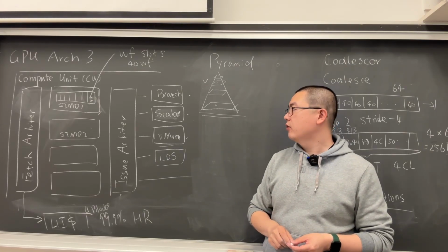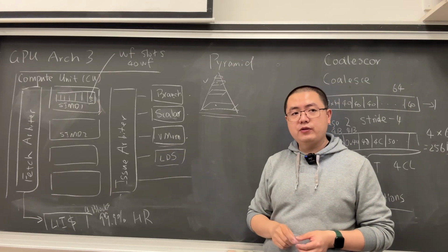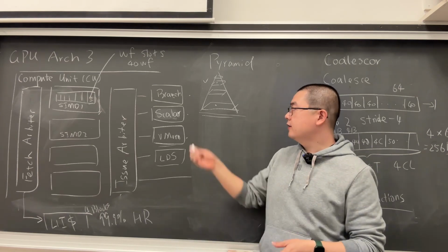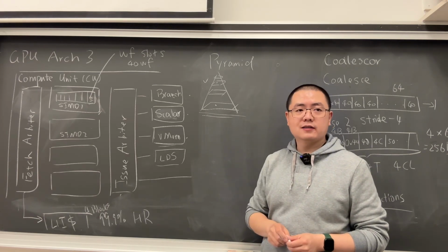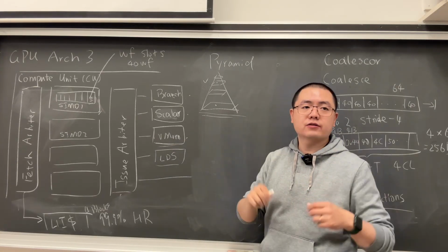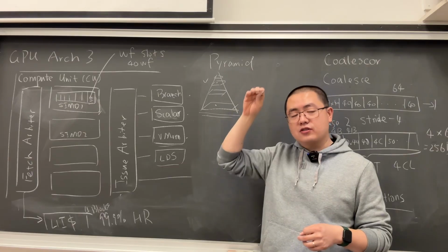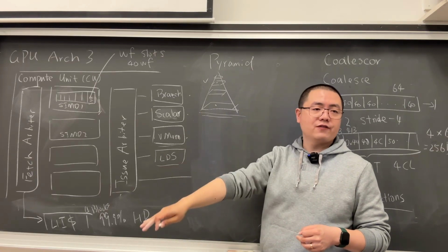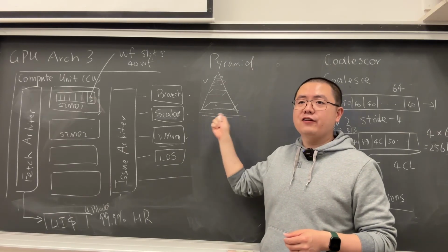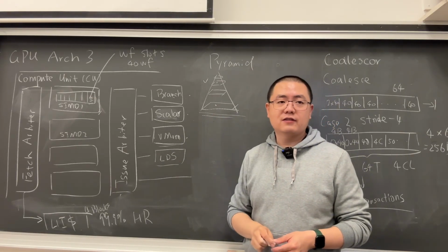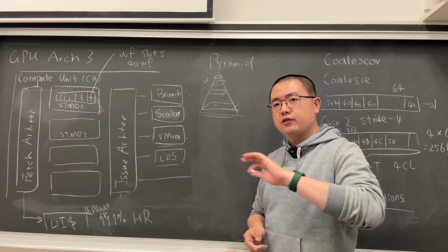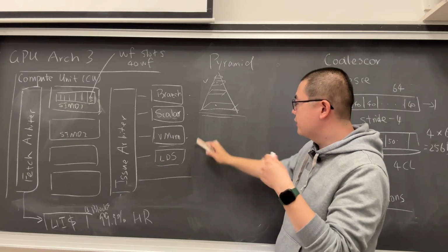And because it's very slow, later on when GPU is becoming more and more important, these two parts separate. If you really need this pyramid operation, you go to the pyramid part. If you don't need pyramid, just do the quick coalescing. Then coalescing may take like 10 cycles, for example. That's why it can significantly reduce the latency from something like 140 cycles down to like 20 to 30 cycles. Not only pyramid, there are a lot of very complex graphics-specific things that are being split from the pipeline, to make it more graphics specific in the GPU architecture.